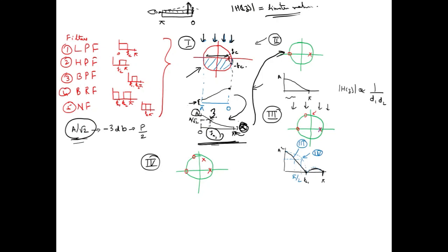When we place a 0 at pi, it suppresses the frequency components that will appear at pi radians. Now, if you look into the amplitude response, at A we are having the gain, and then it slowly dies down, and at pi it becomes 0. Okay.